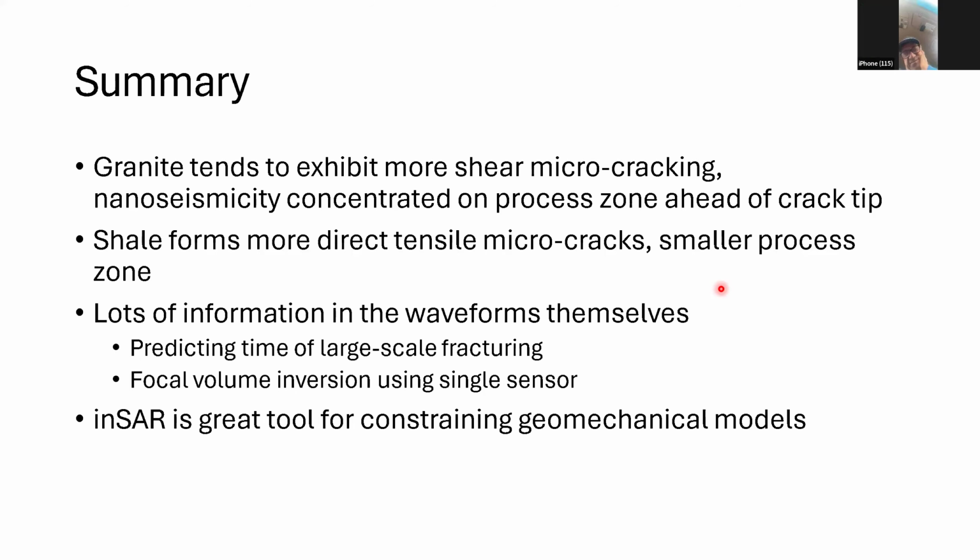Okay, I will take a look at that. That sounds like it might answer a lot of questions I've had as well about where this process zone even is in relation to everything. Thank you so much. Also, it'll change the poromechanics transfer, of course, because when you introduce a hydraulic fracture, the overburden is transferred from solid to fluid. Yes, absolutely. And that transfer is at first only at the face of the fracture, and it dissipates, and generally in poromechanics it is always neglected. I have not seen it ever considered. That's a significant effect. Yeah, absolutely.